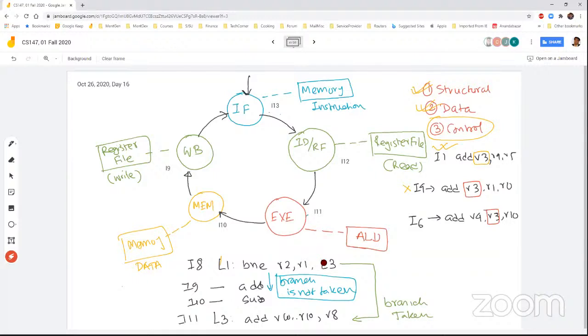But if the prediction was right, there would be no cycle lost during this prediction operation. So this introduces another set of delay, consuming cycles through the bubbles. That's what reduces the performance from achieving the 5x in this case. Question?